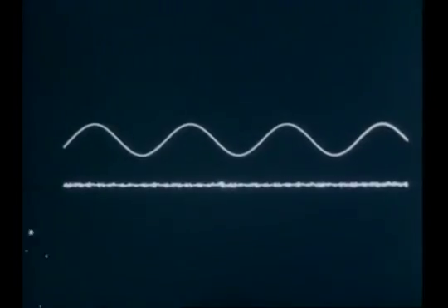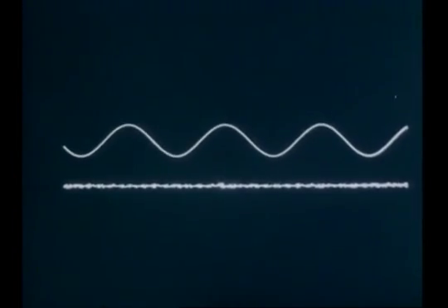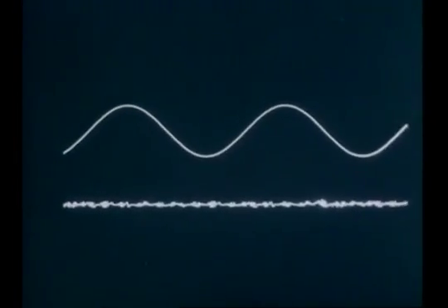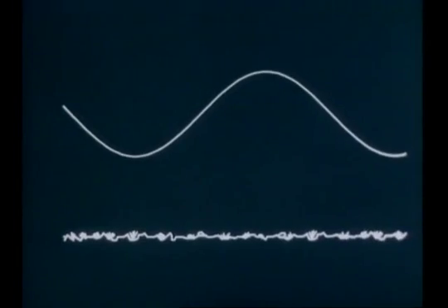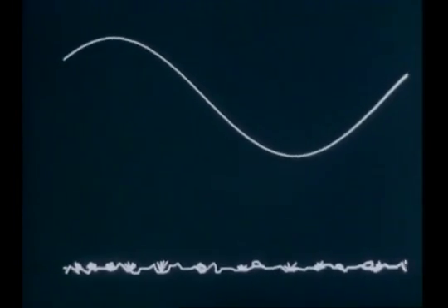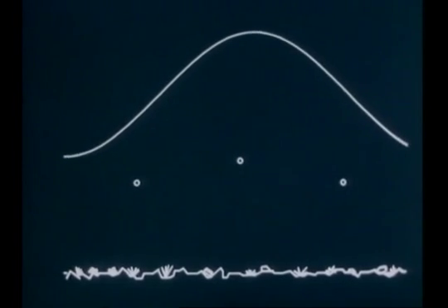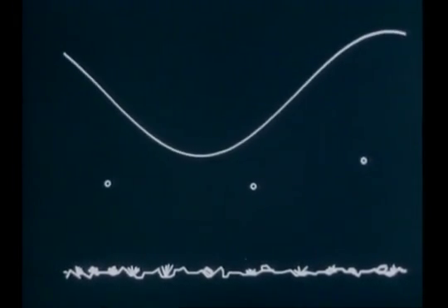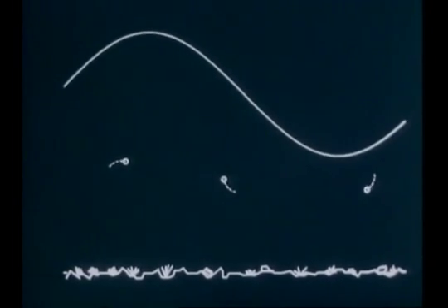It's an advantage of the laboratory coordinates that there's often a frame of reference in which the Eulerian field is steady. Just as we simulated the flow in the contraction, we can simulate the flow under a free surface gravity wave like this. To make things clearer, we have rather exaggerated the wave amplitude. Let's take a closer look. These are moving material points and their path lines.